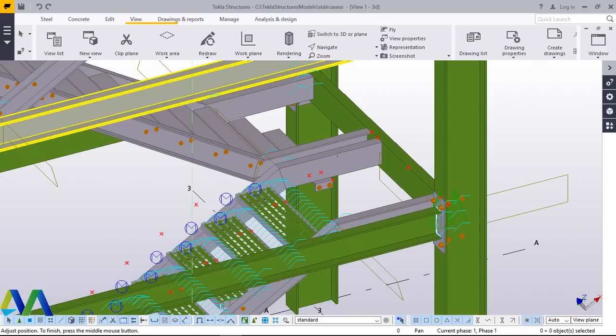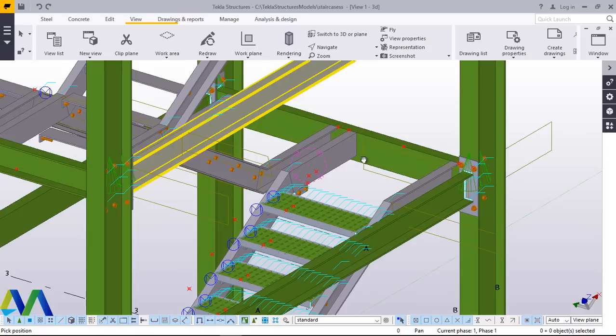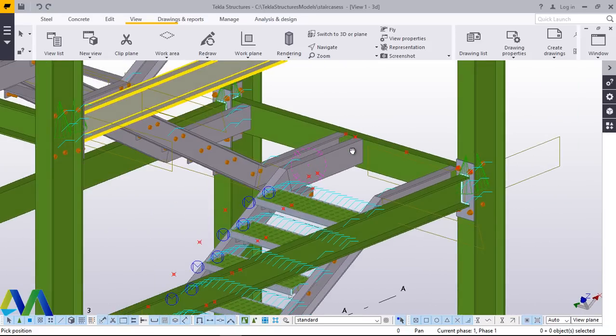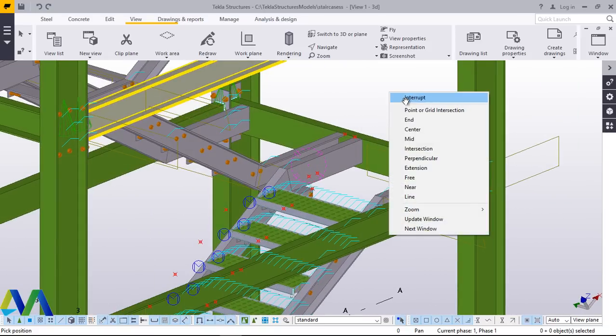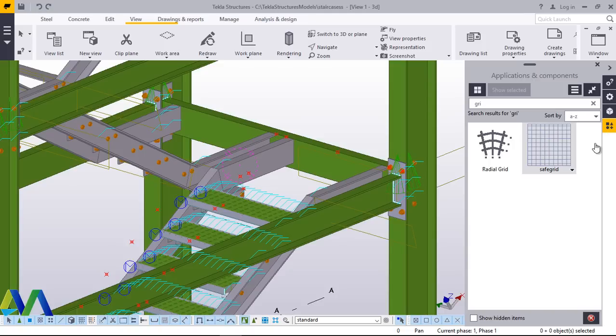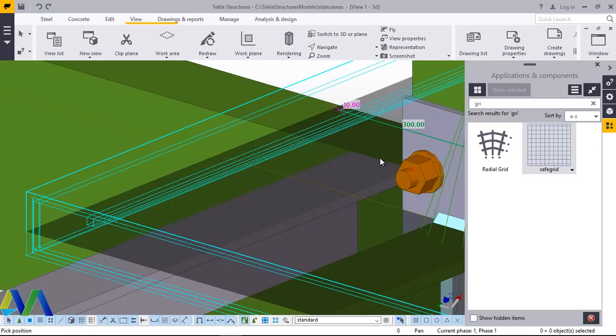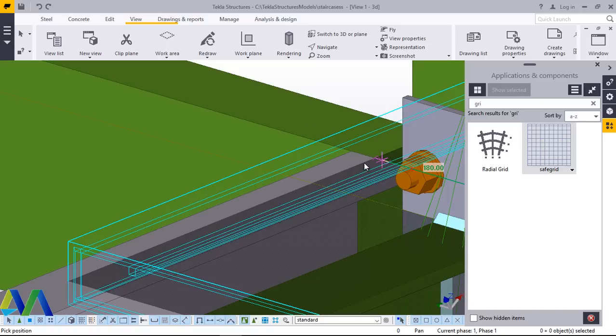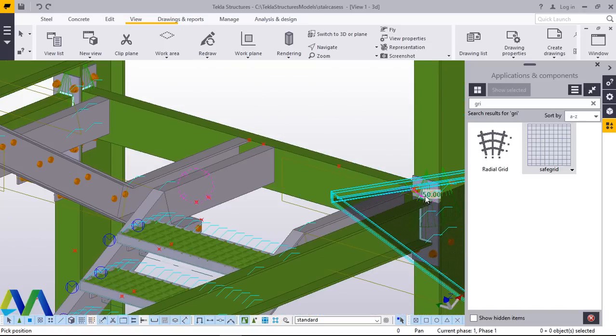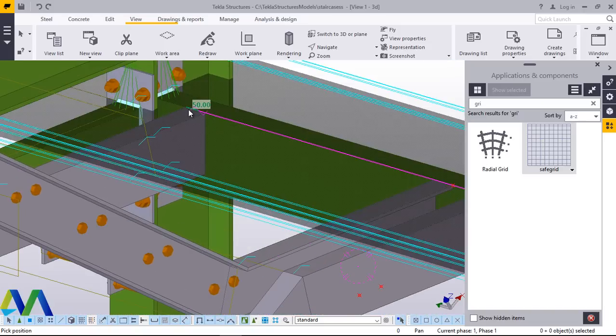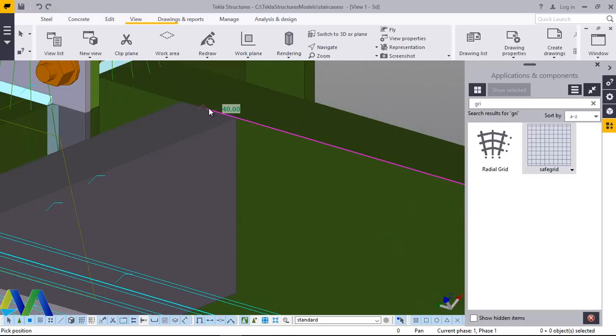Now on the landing, we'll click that, we'll click that and turn it round like that. Then come back to Gratings, pick that, zoom in and out. We'll snap right at that spot and run all the way to this spot, to that spot, and place it there.